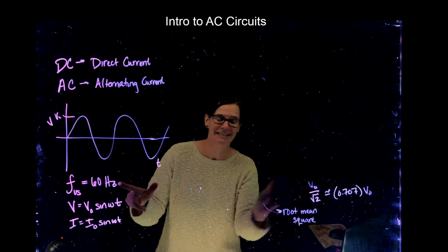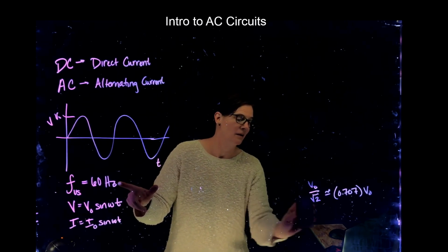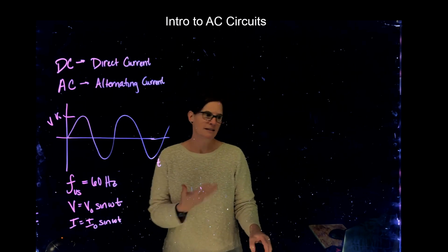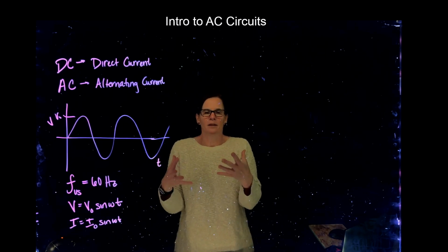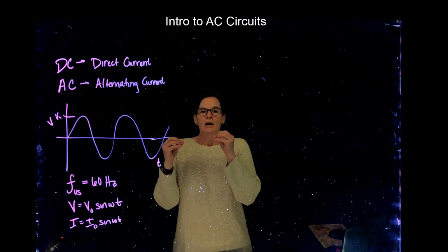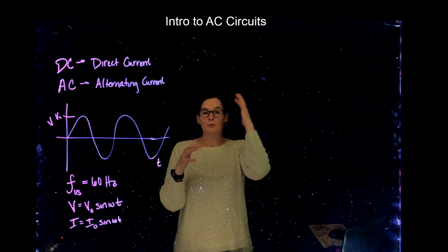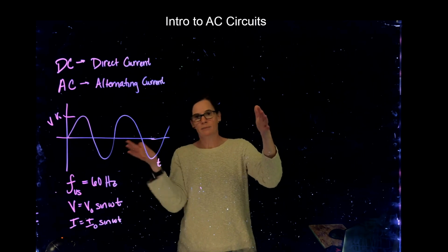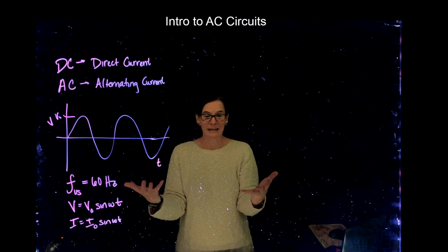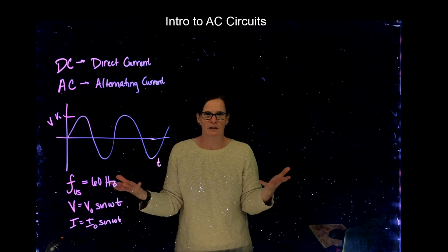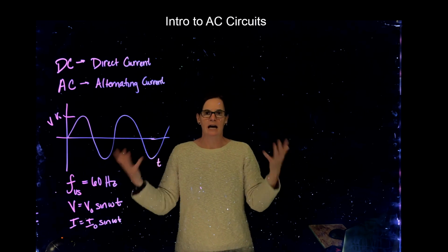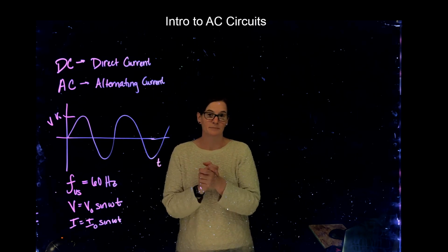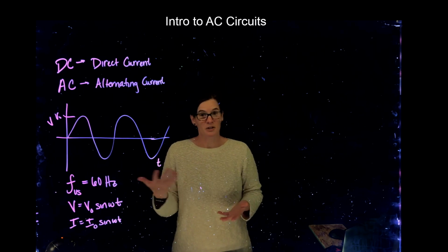It's oscillating at 60 hertz. And so for typical usages, for typical devices like, let's say, a toaster, the example we're going to do with a hairdryer, those heating elements, which are dissipating that power, are shifting between high power and low power, the plus maximum power to the minus maximum power, passing through 0. It's happening, but it's so fast that the heating elements are certainly not cooling down before it's getting that high current, high voltage across it, and therefore dissipating high power again. However, in some applications, you do have to pay attention to it.